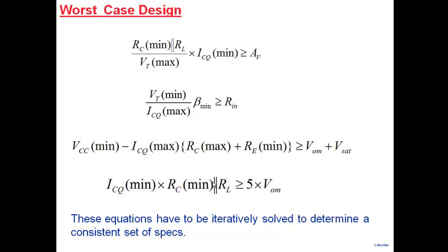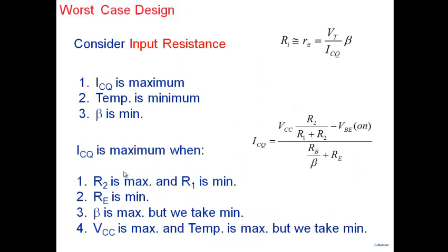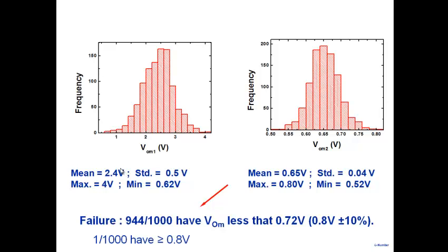Okay, and as I said, in MATLAB and all that, you can very easily generate a random variable with a certain mean value and a certain standard deviation. So you can run your simple MATLAB program, and you can get these plots, histograms, of how your gain will vary and how your input resistance and output resistance will vary, all of those quantities. And at the end, you can check the design that you've done under this constraint,